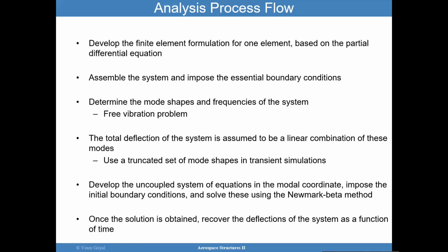loading condition. So I showed you how you can develop an uncoupled system of equations in the modal coordinate and how you can impose initial boundary conditions. And then you can use the Newmark beta method to really solve the problem. Once a solution is obtained, you can recover the deflections of the whole system.